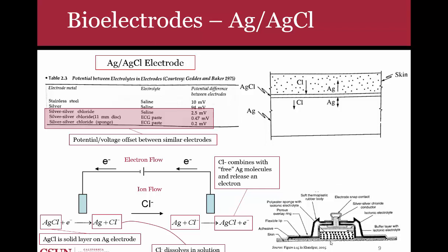So this is the interface where you can convert ionic currents like silver and chlorine into electronic currents on this end here. And so you just have a couple of mechanical structures here that are to basically attach and adhere to your skin, but effectively you're creating like this interface between metal and chlorine or silver chloride and your skin.